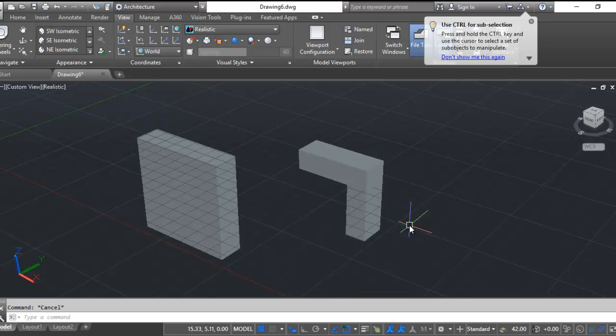Now I also have a few cylinders to add to the end of these shapes, and now's the time to do it. So I'm going to type in the command cylinder, and this again is what you would have on your 3D ribbon if you had that turned on. So I'm going to pick just out in space as my base point. Let's look at D for diameter and 1. And now my height is 0.75. So follow the prompts on the screen to get that.